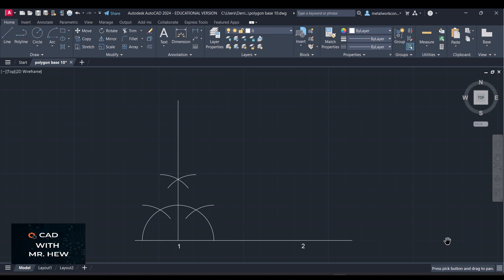So what you would do, you would draw arcs from center 1 to give you this semicircle here. Then the same radius, we will put it at where the semicircle intersects the baseline and mark an arc to give you this arc. Same radius. Likewise, you'll put the compass over here, or the center point if you're on AutoCAD, and you'll draw an arc the same radius that you started with. Where these two arcs intersect the previous arc, then you draw arcs of the same radius from this point and that point. Okay, is that clear? Good.